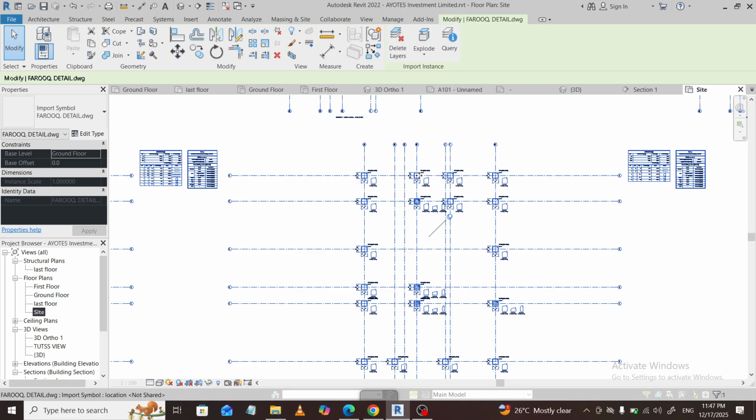Once the CAD import is selected, you'll see special tools become available just for this situation. Now head to the Modify tab. The Explode tools only appear when a CAD file is actively selected, so if you don't see them, double check that the import is highlighted. You'll notice that Full Explode is often disabled for many DWGs, and even when it's available, it's rarely the best choice because it can create an overwhelming amount of fragmented geometry.